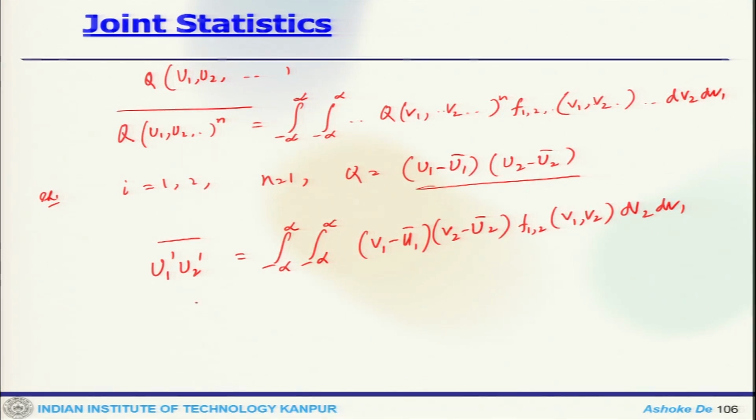So essentially, let's say this is U1 and this is U2, and this is U2 bar and this is U1 bar. So the mean correlation goes like that, where things could be scattered in this fashion. These are two velocity components U1 and U2 in a scatter plot, and this is how the covariance shows the correlation between these two variables.